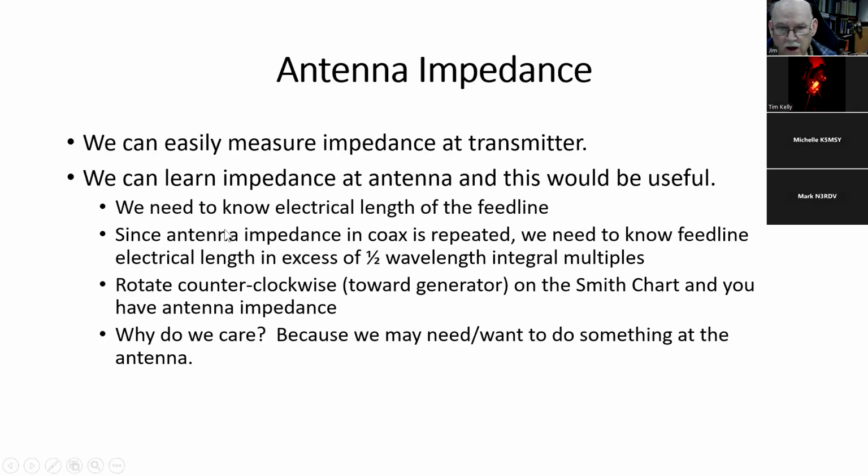That's why we care. We can easily measure what we have at the transmitter, but we might want to know what the impedance is at the antenna, and then we can make a decision as to whether or not and what we're going to do at the antenna. You may not need to, but it would be good to know.